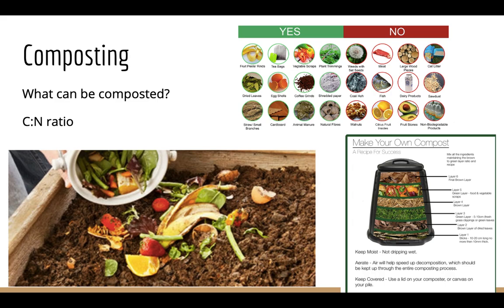And then your green material would be your fruits and vegetables. So you would layer your carbon stuff, your brown material, with your nitrogen stuff, your green material, and then you want to make sure this stuff gets turned over frequently, because that's going to ensure aerobic decomposition, decomposition in the presence of oxygen, which won't produce methane gas and will break down more efficiently. The respiration activity of microbes generates heat that kills pathogenic bacteria. And that heat relies on this optimal carbon and nitrogen 30-to-1 ratio and that turnover rate.